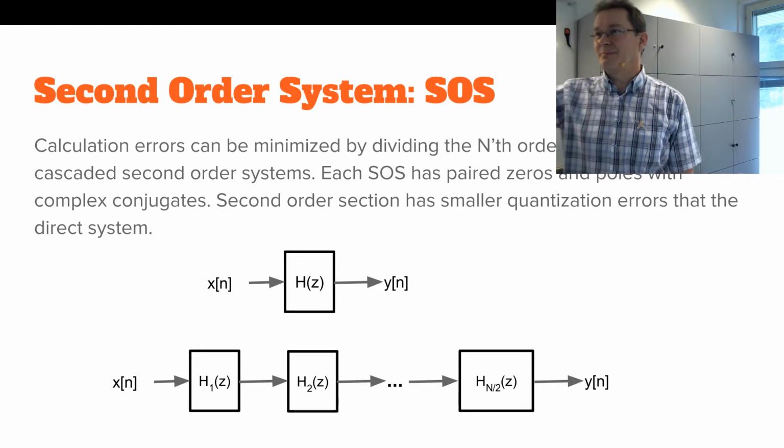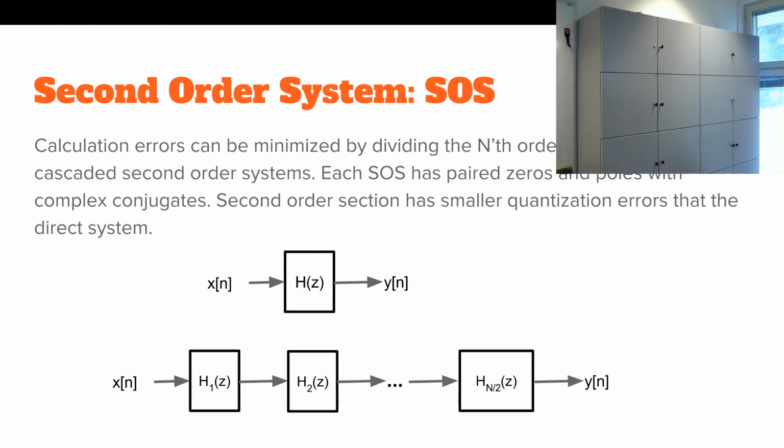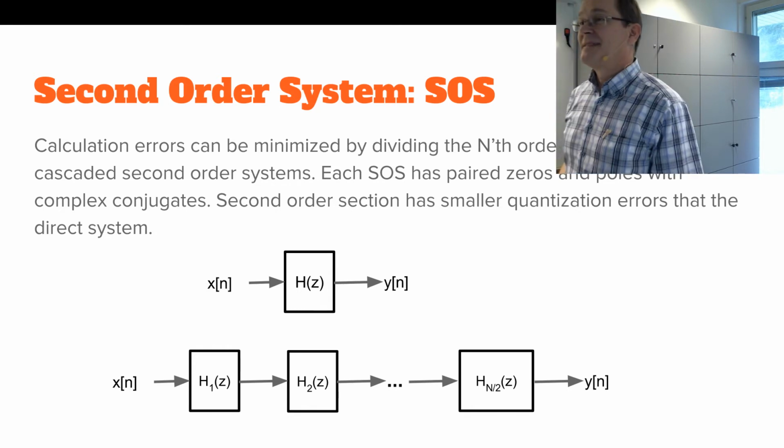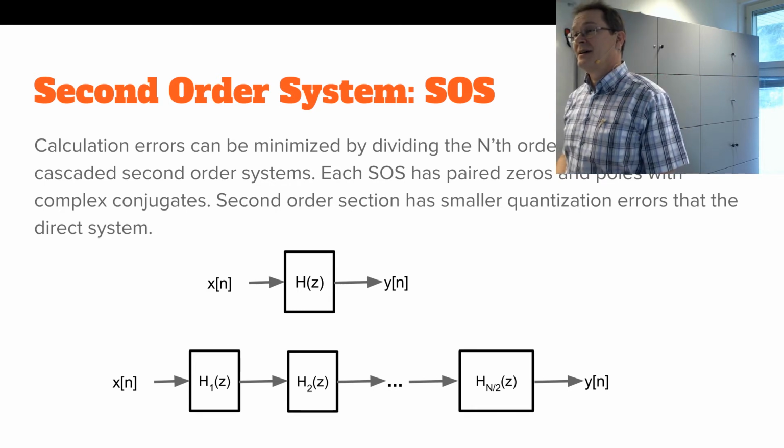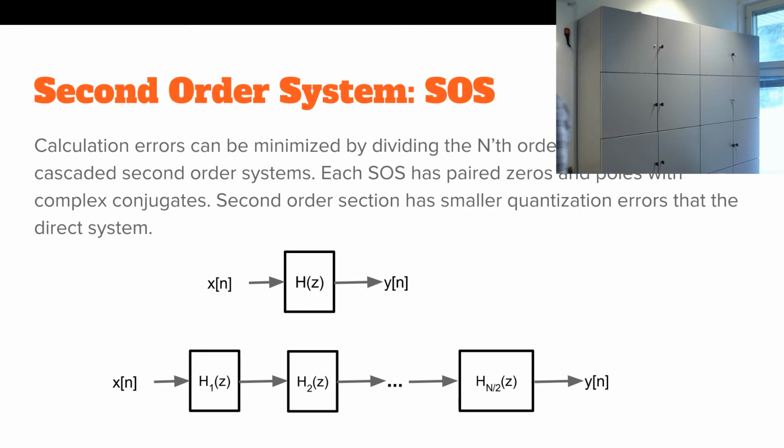And pipelining and parallelization of this one. So that looks like pipelining. Just thinking that if you have, for example, a really big filter at first, you want to piece it down to second order systems. In the end, you have like 20 different filters that are connected to each other, and you always have to compute the first one, and the second, and the third. Well, yes, you can, but then you'd also start making blocks out of it,